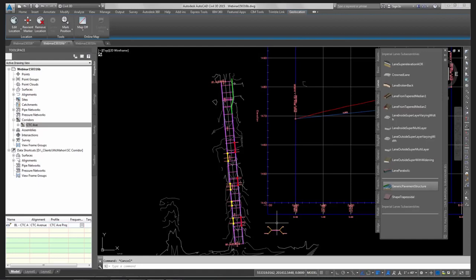So that would just be kind of like what I did with my turn lane right there. I had here a 12-foot, if you want to call it, parking stripe width, and up in here I had a 24-foot parking stripe width, and then I just had a line that connected the two. So it always targeted. So that would be a way to do the parking width, or parking stripe width. I just did it as a turn lane.